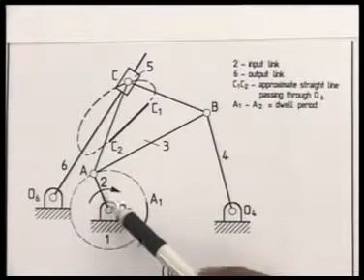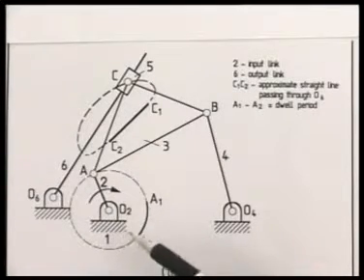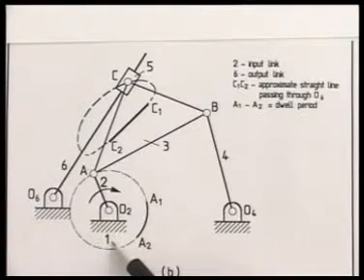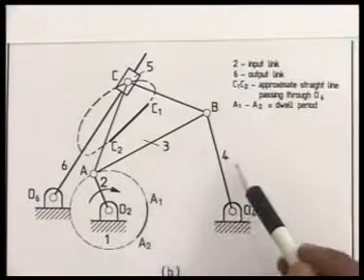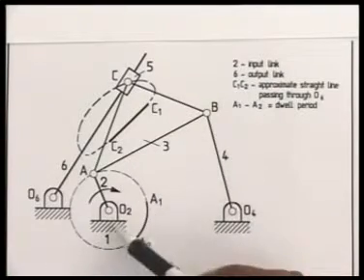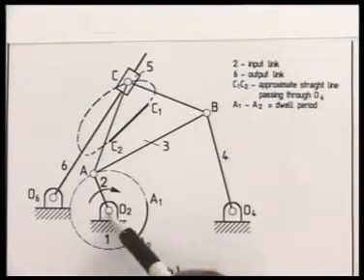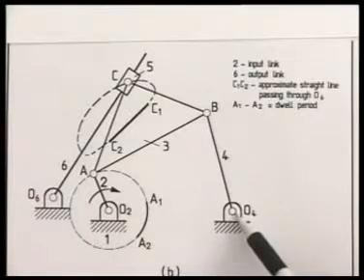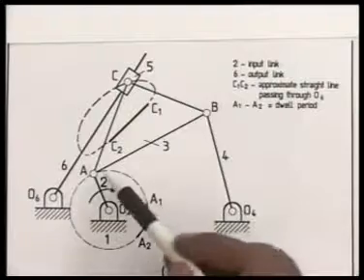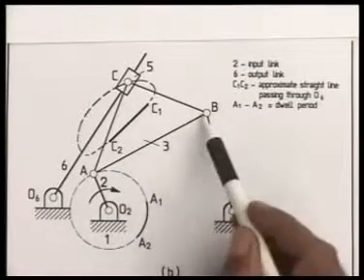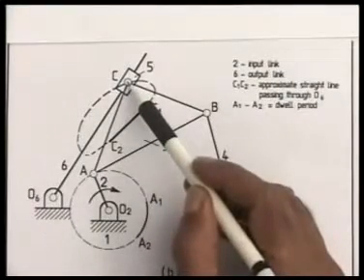This is the kinematic sketch of a 6-link mechanism consisting of the fixed link, link number 1, link number 2, link number 3, link number 4. This 1, 2, 3, 4, that is O2, A, B, O4, constitutes a 4R planar mechanism. And on this coupler AB, I take a point C, this coupler point.